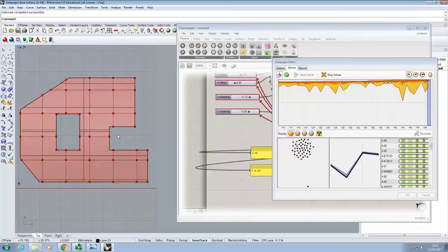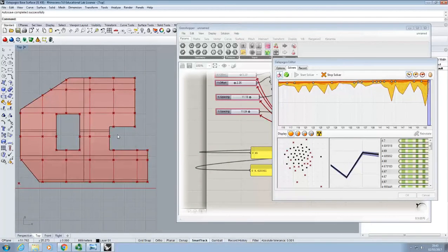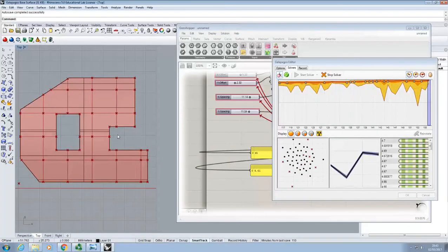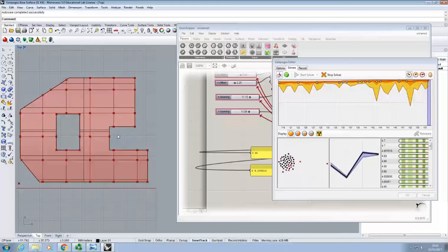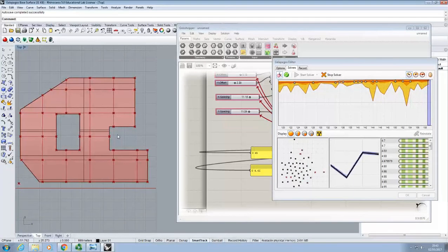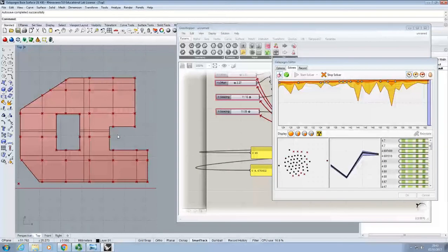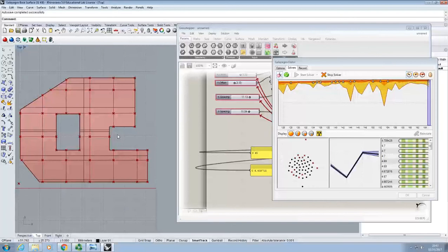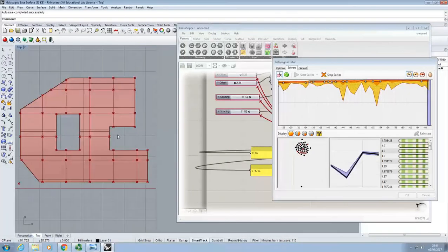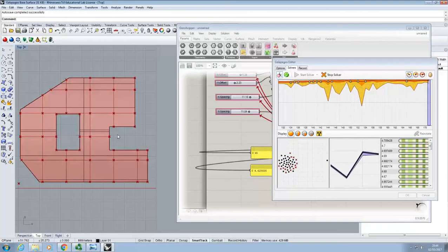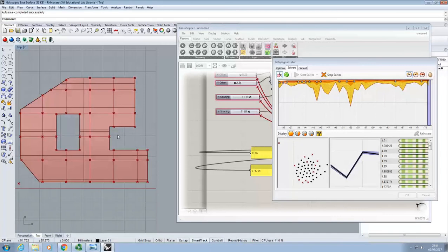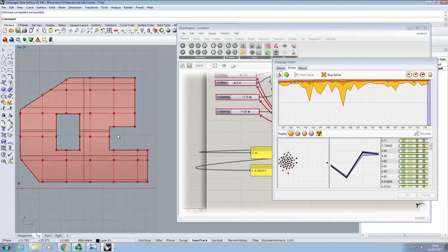So with optimization programs like this, and even stuff like automating beam sizing, very often you'll want to apply some sort of engineering judgment to the results as well. So for example, I've done beam optimizations where it just churns out and gives me the optimum beam size for each individual member in a building. But if you were just to give that to a contractor where every single beam was a different type, you probably wouldn't be too happy with that. So then you need to apply a little bit of common sense to reduce those into a certain number of groups and so on and so forth.